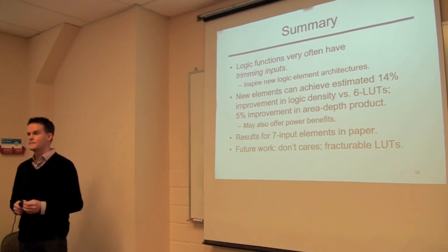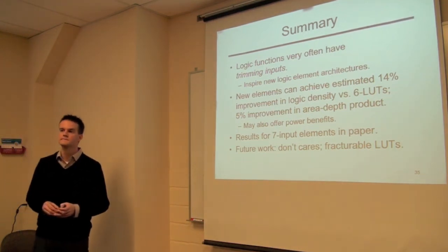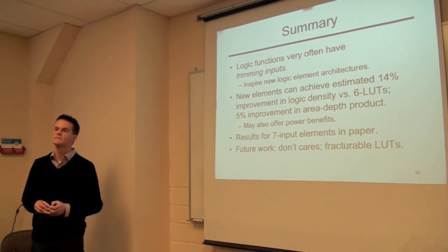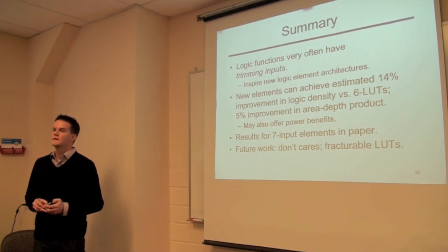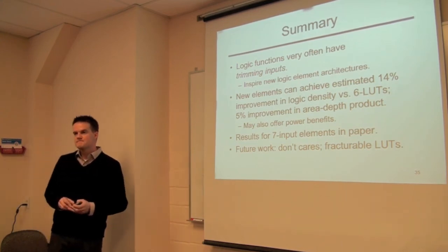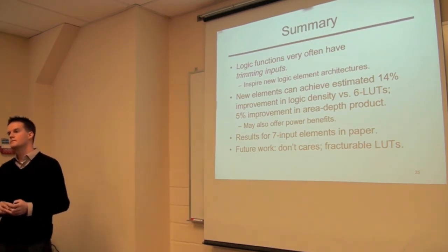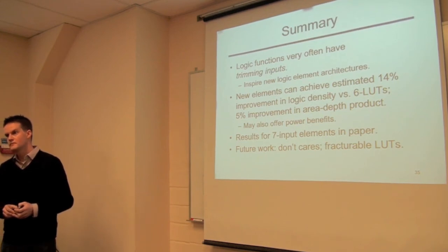Greg: So I guess a power question. When you're doing mapping, do you think your choice of cofactor bit would have a significant impact on dynamic power? Okay, in what sense, I guess? Well, the cofactor bit is choosing one part of the circuit or the other. So if you chose a bit that happens to switch a lot versus one that doesn't, it seems like that might have more or less of an impact on dynamic power.